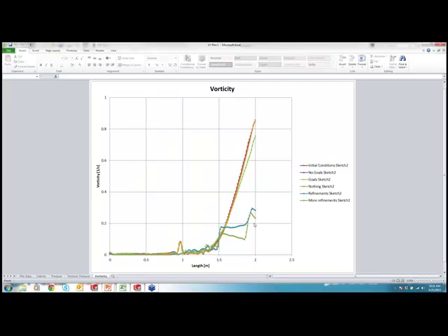And so we have a much lower vorticity, even though overall the element is going to have more vortex at the bottom of that square channel. Our line that we're looking at across the center, where the flow profile is, is not included in that vortex nearly as much, so it loses a lot of its vorticity in this line. If we were to look at a cut plot of vorticity, you'd see a high area of vorticity underneath the square channel in the refined copy.